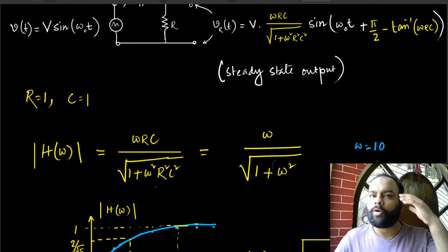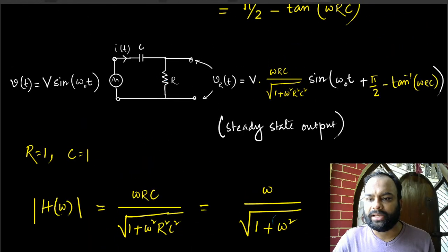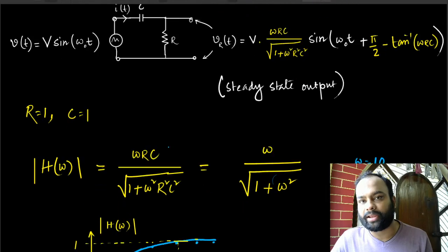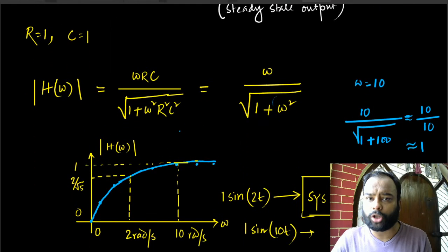And of course, from your very simple understanding of circuits, if this is a lower value resistor, then the capacitor gets charged or discharged quicker. The capacitor will be charging or discharging quickly. And if the resistance has a higher value, then the capacitor will be charging and discharging slowly, because of the time constant, right? That will definitely have some effect on the final output here. Also, one point to note is that if R has a different value, then this is going to be different, right?